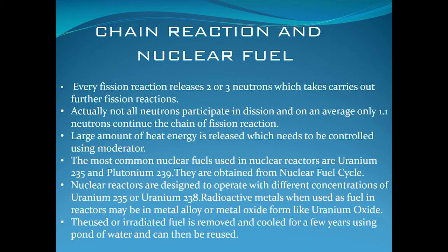The nuclear fuel cycle may result in uranium 235, which is a natural radioactive metal source used in most nuclear reactors. Most nuclear reactors may also have fuels like plutonium 239, uranium 238, or thorium 232. These nuclear fuels are inserted in the initial stage of a nuclear reactor and can last in a nuclear reactor for a period of a few months up to 5 years, and are part of the initial cost as was discussed in the previous video lecture.